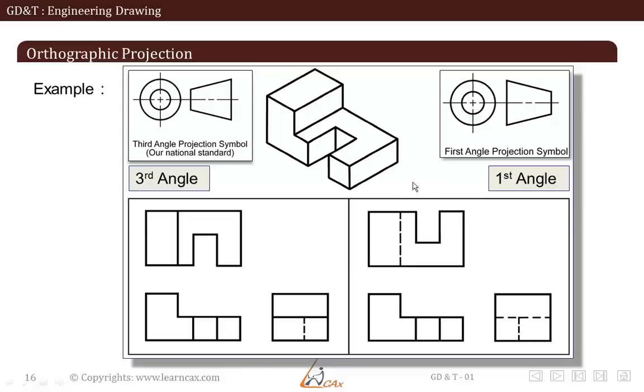When viewed from the side face and keeping the projection plane behind the part, it is obvious that the only face visible to that plane is this back face. Hence, that is the only dark line visible in the orthographic projection. Rest all lines will definitely become dotted as they are not visible from back side.